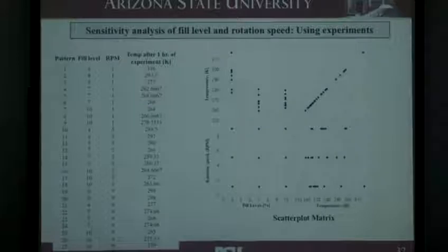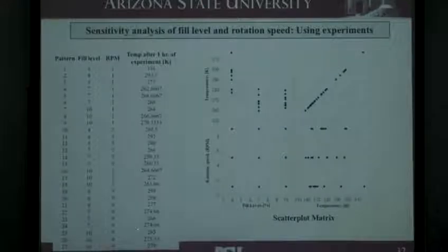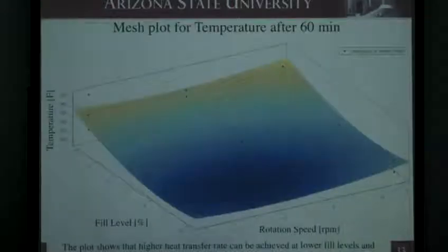And we did some experiments. Just for contact conduction, we looked at a fill level between 4 and 10% and rotation rate between 1 and 9 RPM. These seem like really low values, but these are actually really industrially relevant values, so we wanted to look at those. We just recorded the temperature after an hour for each of those conditions. This is when we just got our setup, so we did stop the drum and stick in the thermocouples, and right now we're still working on the calibration of the thermal camera. But what we found is that